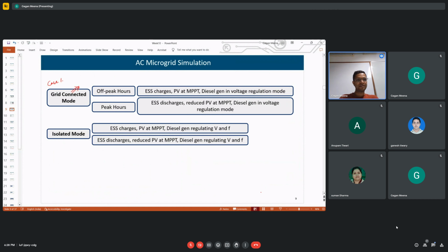That is why they are only dependent on their own. And G12 and G21 are the transfer functions which relate one with the other voltage. So the first one, I21, becomes G11 into VO1 plus G12 into VO2. So it is dependent upon both the pole voltages.